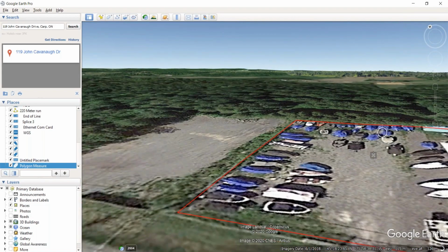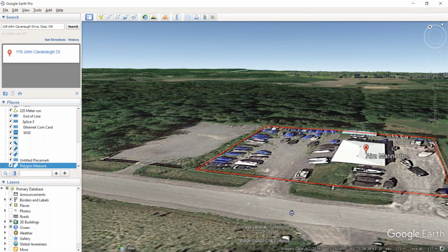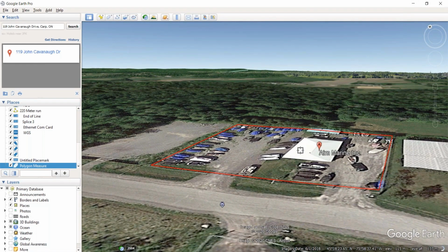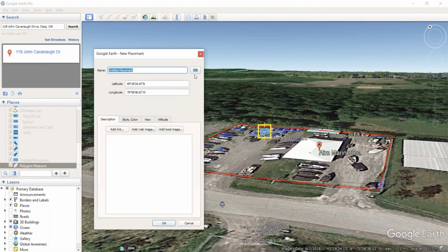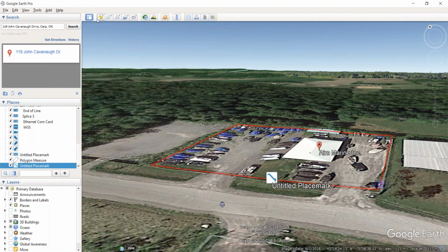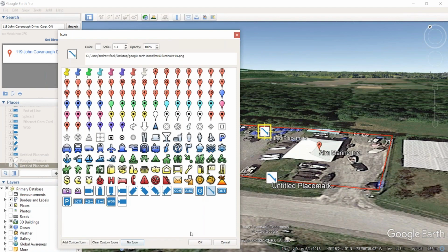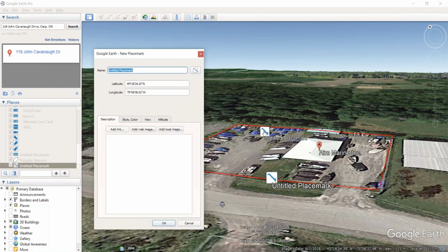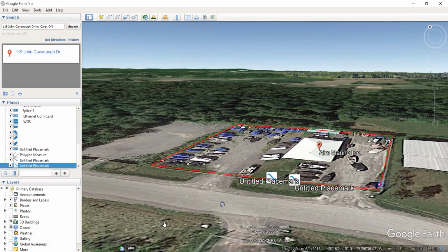Now, the greatest part about this whole site here is everything we needed was right at our disposal. We had our equipment room in here. We came right out there. We mounted a processor, and then we started laying out our lights one by one by one. Now, I do have a light luminaire, and I'd encourage you not to do this just because the spacing on the lights is every 6 meters, and it doesn't look very good. So if I add this one, and then I go add another one again, probably not the greatest idea. However, what's very important is to maybe identify one that becomes your access point, because that's your communication back. And then afterwards, you just mount them around the system similar to a fence sensor.